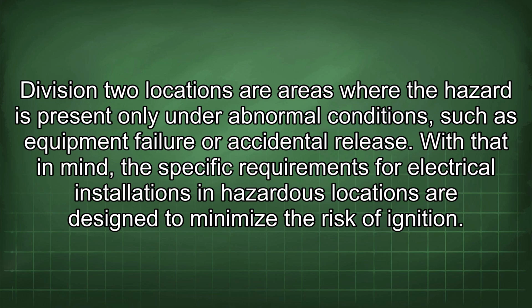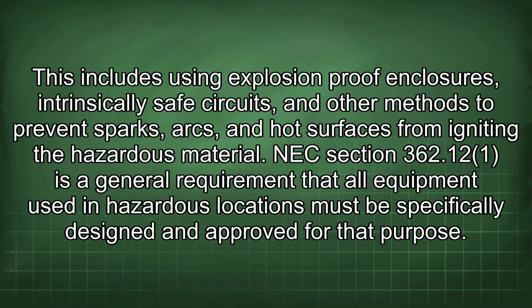With that in mind, the specific requirements for electrical installations in hazardous locations are designed to minimize the risk of ignition. This includes using explosion-proof enclosures, intrinsically safe circuits, and other methods to prevent sparks, arcs, and hot surfaces from igniting the hazardous material.